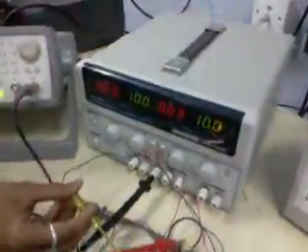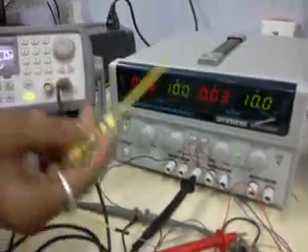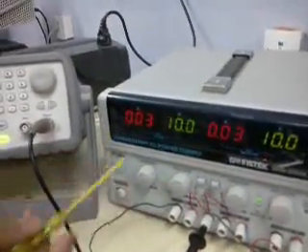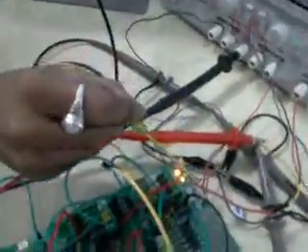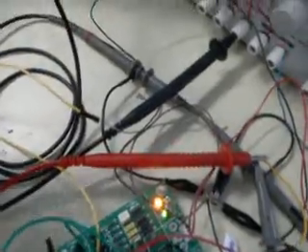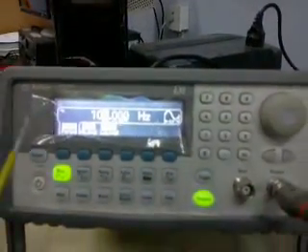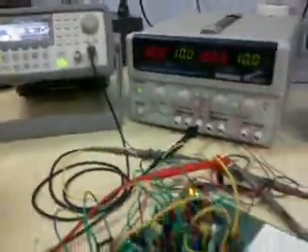This is the power supply section. For this we have used a power supply, and we are taking plus 10 volt and minus 10 volt voltages from here. And here there is an input that is simply the AC input coming from the function generator, and the input varies from 100 Hz to 1 kHz range, and the output is shown in the oscilloscope.